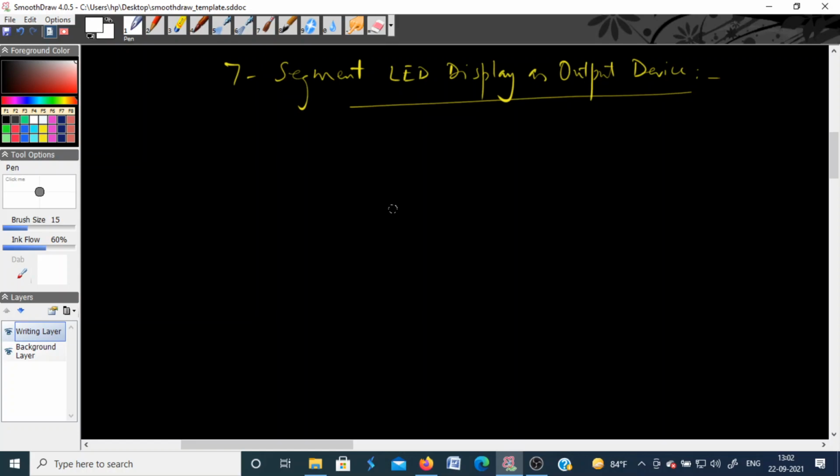Okay, we have discussed in the last class how you can interface the LEDs with the microprocessor. Just to revise, we have taken a NAND gate, in which the inputs were connected to A0 to A7. So it gives a unique address pulse, that is logic 0, when all the inputs are at logic 1. So the address of the device was fixed using this circuit, which is FFH.